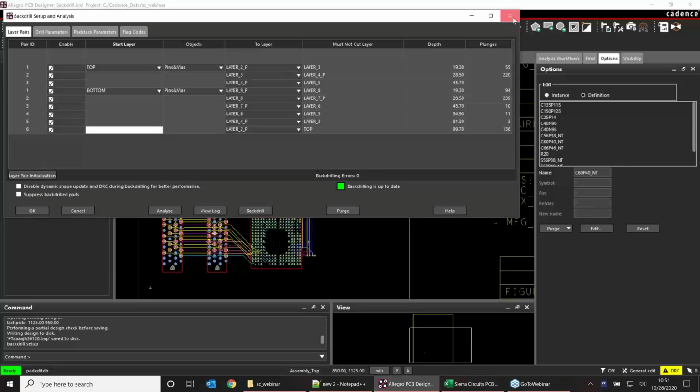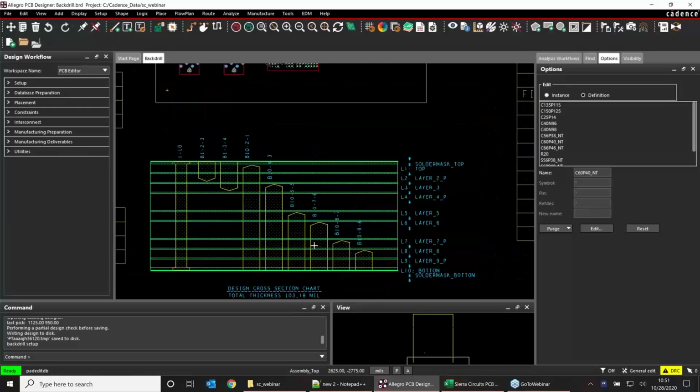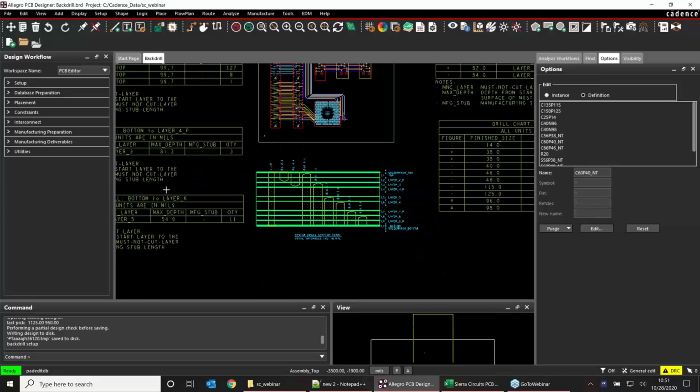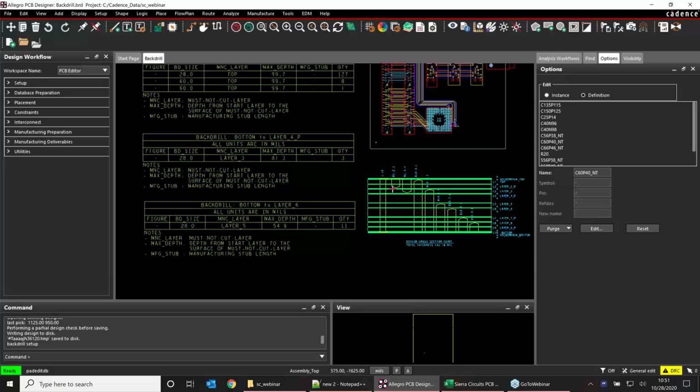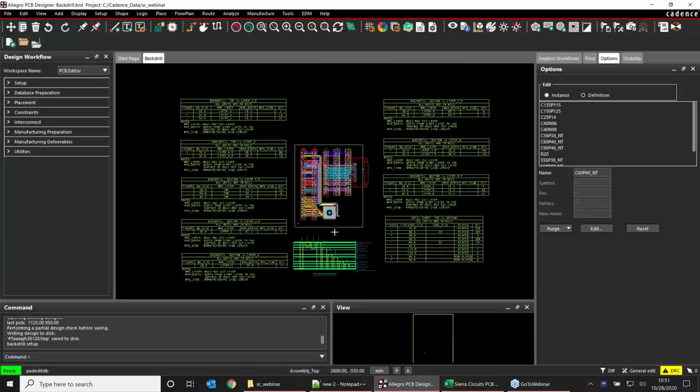Out of that, you can get some manufacturing data here that is pretty interesting to look at. You have your core via that goes all the way through, and then you have a few of your top layer vias. Notice we only see 2 here because we're not actually using that third one. And we have a number here coming from the bottom up where they cut through a certain number of layers, but not through others. You can see that graphically here, and here are some of the drill legends that your manufacturer will be interested in seeing for some of those depths. It's also going to be attached as a drill file that they can plug into their machine so they know exactly where to back drill those out.